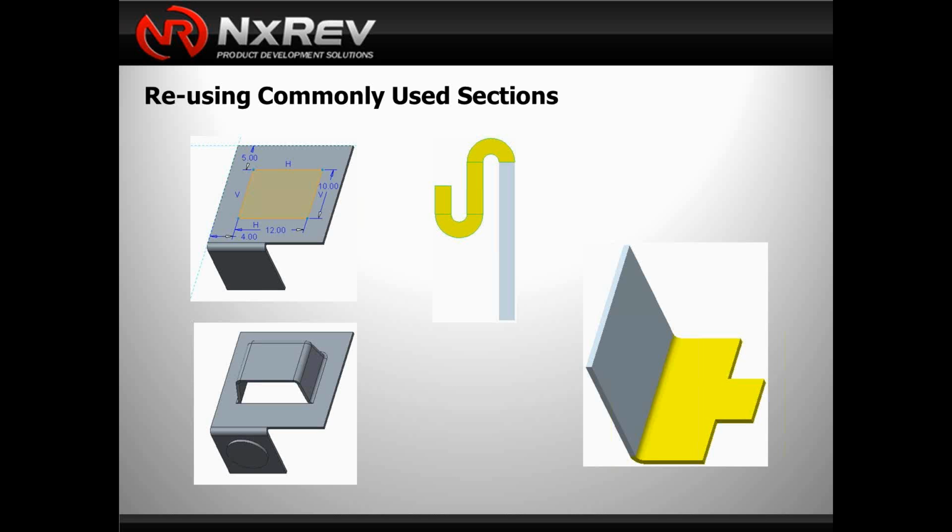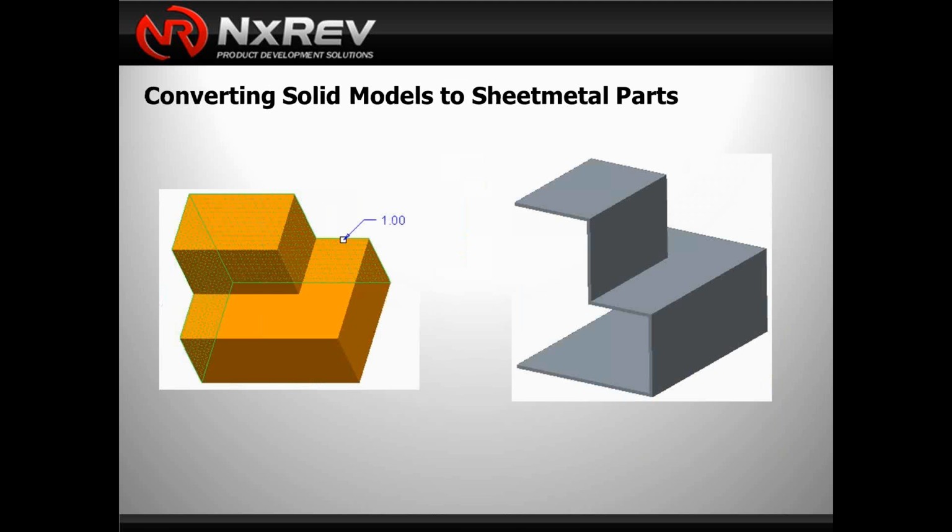The other is you're able to create sketch forms now, which is a very powerful tool. You can bring in some library of sketches, maybe a louver or something like that, and then build out that geometry all within one tool, the sketch form tool, that can add drafted surfaces or angled surfaces, and rounds to the intersecting edges of the rest of the part, and also to the rest of that feature. So that's a nice thing.